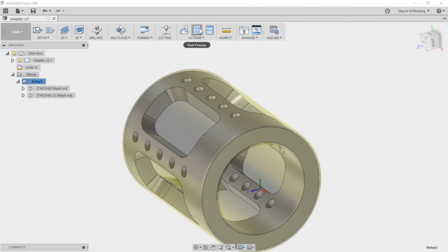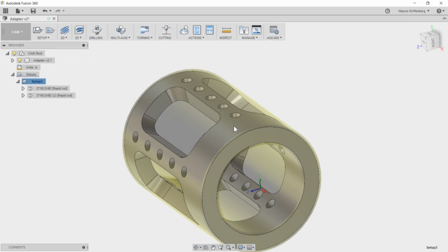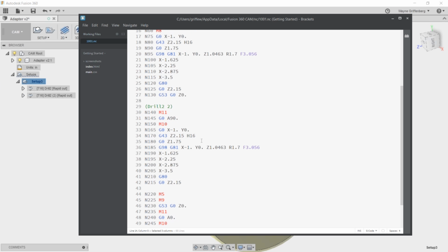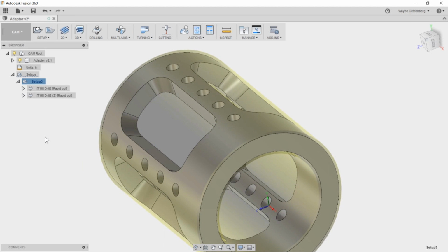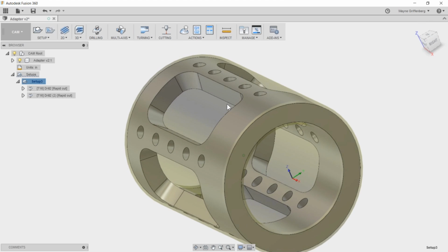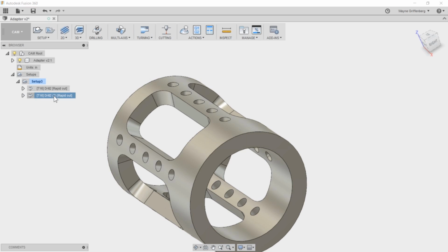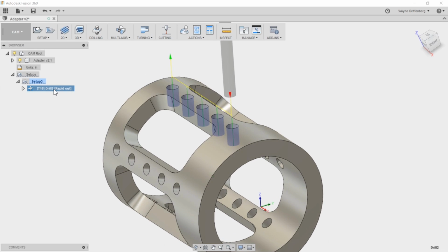And of course, if I post out both of these, now you'll see in the first one, there's the A18. And now in the second one, we're going A90 degrees for drill number 2. And then we're returning back. Now you can think, well, I can do that. But now I've got to copy 5 of these down, and what if I have different holes and so forth? It could be a pain. Well, here's another way you can do this in a nice way. I'm going to delete the second holes I did, and now I'm going to make them into a pattern.